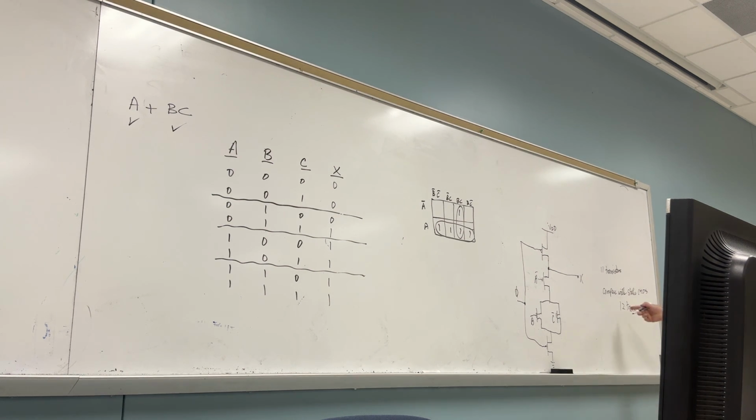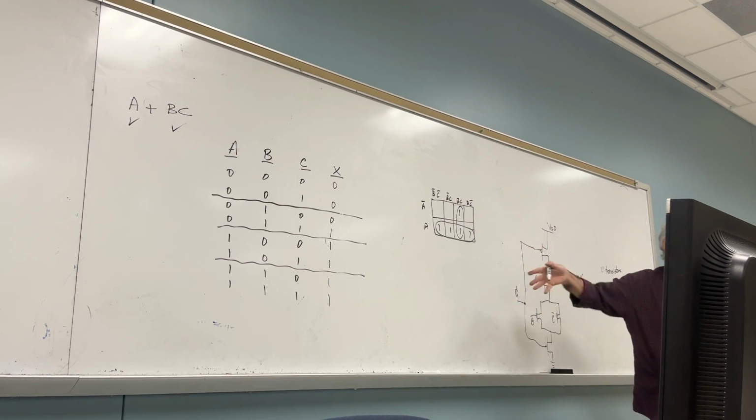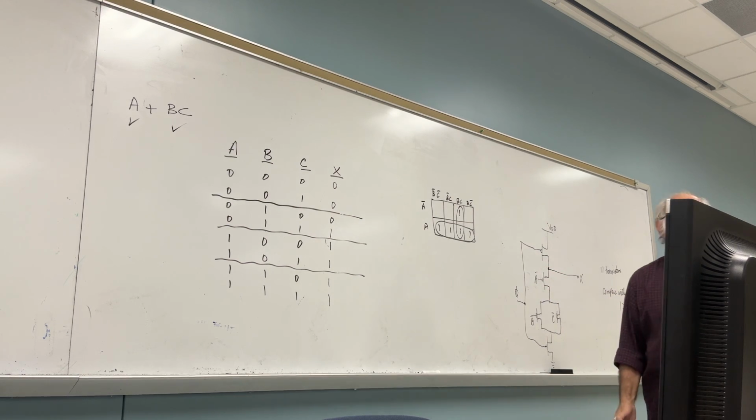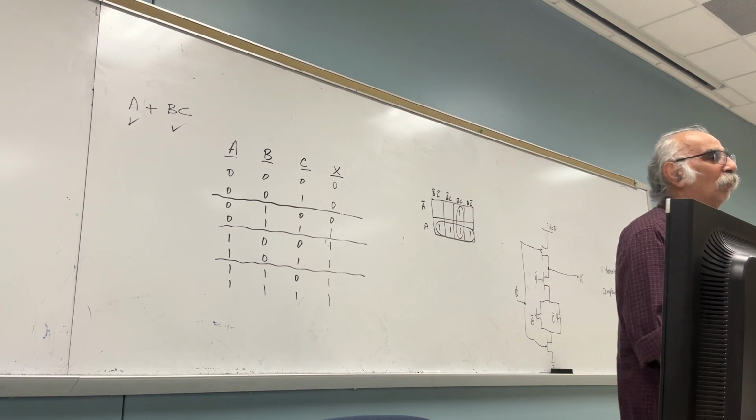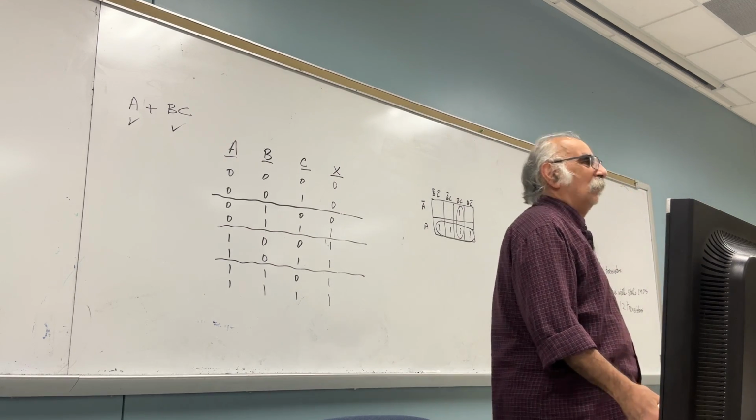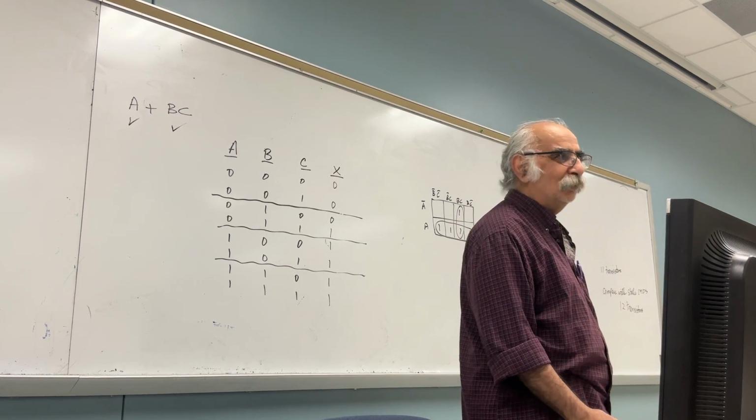By the way, here you might tell me 11 transistors, 12 transistors, the saving is not much. Do you agree? Yes. The saving will become better and better as the fan in increases. Fan in means the number of inputs to the logic. The higher the fan in, the saving for the dynamic logic is greater, better. Did you get it or not?